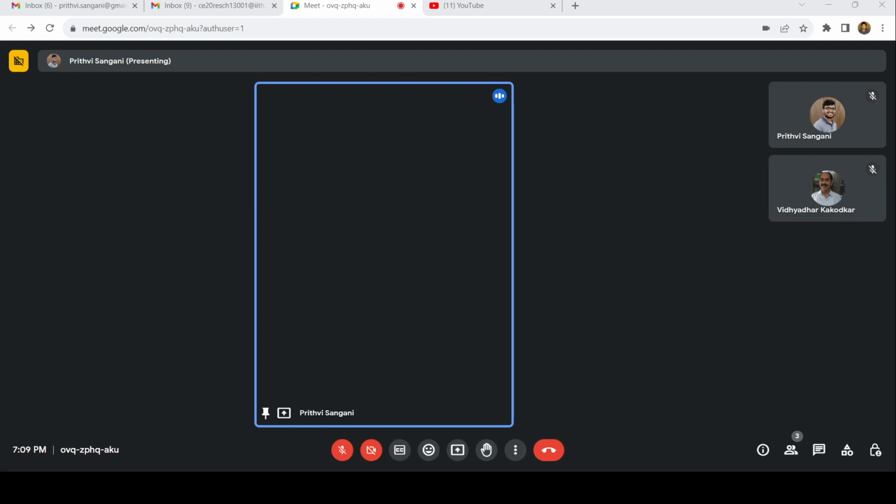So delta 1, first let us find what is delta 1. Delta 1 is nothing but sigma fi ui li by AE. So only consider this part. I'll just write down, maybe we can make a table or column, and then it will be easy for us to write those down.